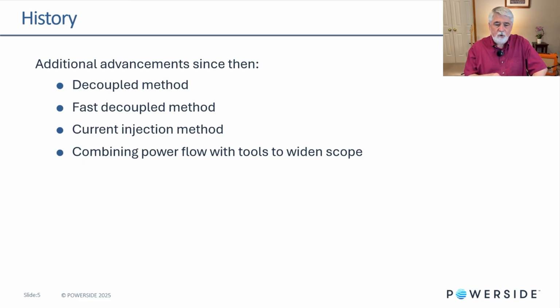Both decoupled and fast decoupled happen to work really well on interconnected power systems, which are well conditioned for them because of the high X/R ratio within those systems.